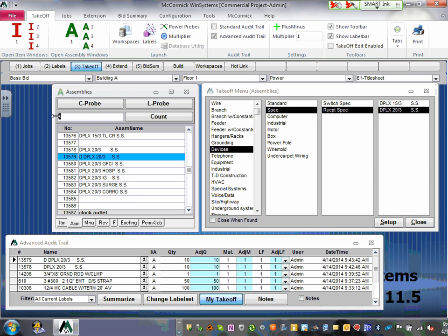Okay? Then right underneath it, we have duplex GFCI, hospital, IG, and isolated ground, surge and core, duplex core. I can't remember what this is. So most of what you're going to be doing, guys, is either duplex GFCI or double duplex or duplex non-GFCI. Isolated ground, there's a couple of isolated ground guys in the commercial building that we're using, but they're using it in the furniture though. Any comments about devices?